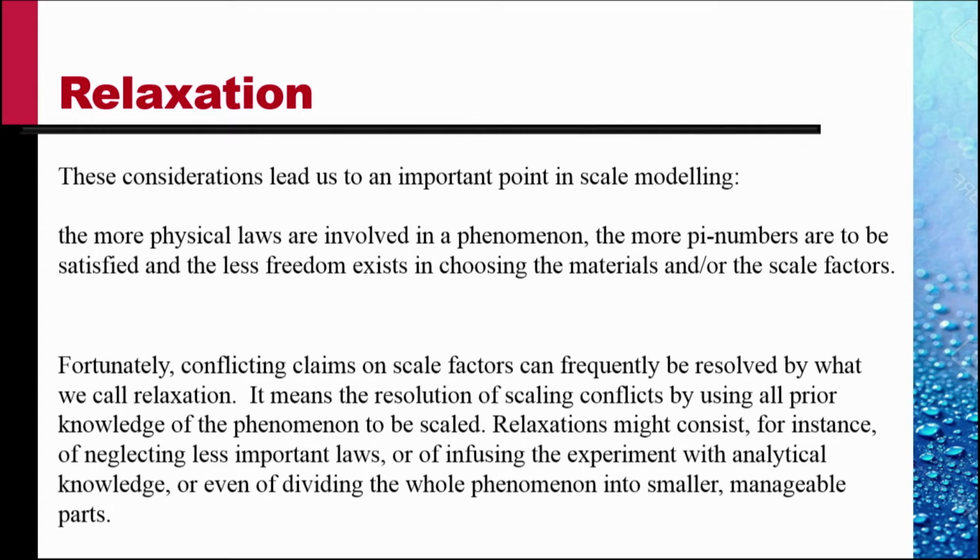Fortunately, conflicting claims on scale factors can frequently be resolved by what we call relaxation. It means the resolution of scaling conflict by using all prior knowledge of the phenomena to be scaled. Relaxations might consist, for instance, of neglecting less important laws or of infusing the experiment with analytical knowledge or even of dividing the whole phenomena into smaller and manageable parts.